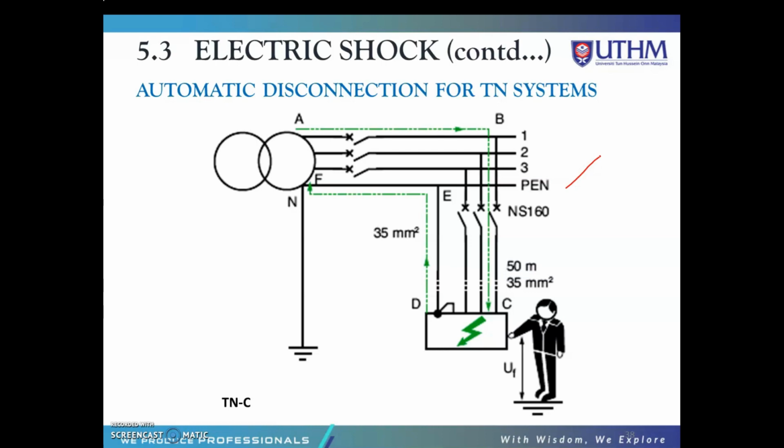High fault current levels allow the use of overcurrent relay protection, but can give rise to touch voltages exceeding 50% of the phase to neutral voltage at the fault position during the short disconnection time. In this system, we can use circuit breakers and fuses, and RCDs may be necessary on the TN-S earth systems.